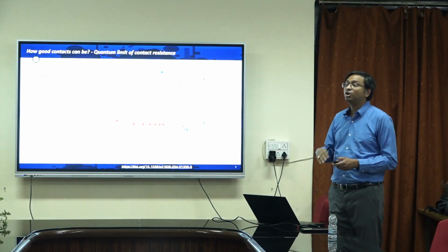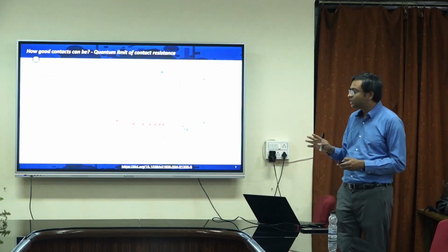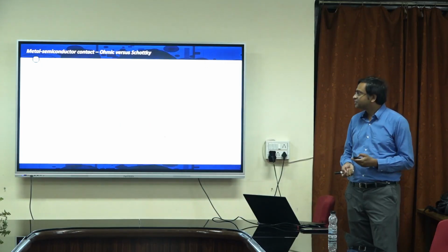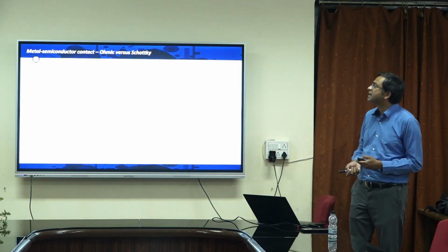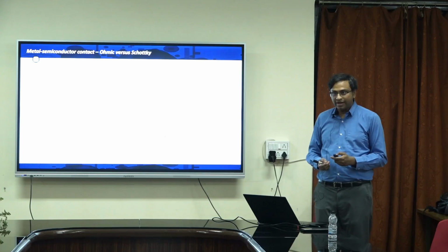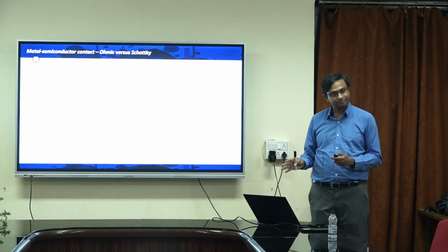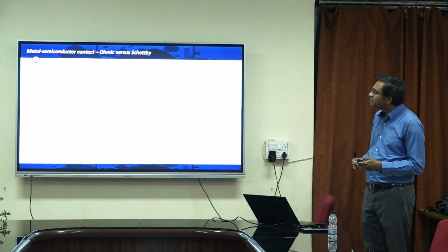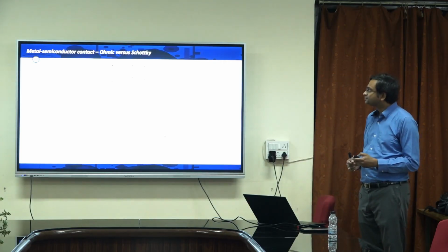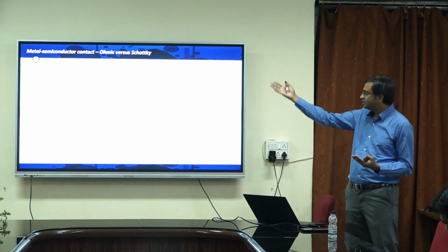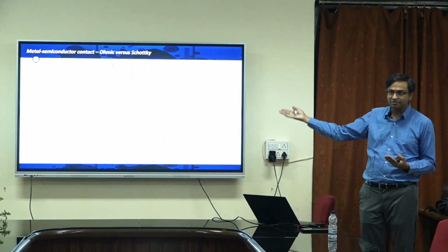So this is all for an ohmic contact, but metal 2D contacts are far from being an ohmic contact. Okay, so we will start talking a little bit about metal semiconductor contacts and what it means to be ohmic versus Schottky barrier. Okay, this is going back again to a very basic drawing board. So now when you have a metal, metals only have a Fermi level, and therefore it is determined by a work function which is phi m.